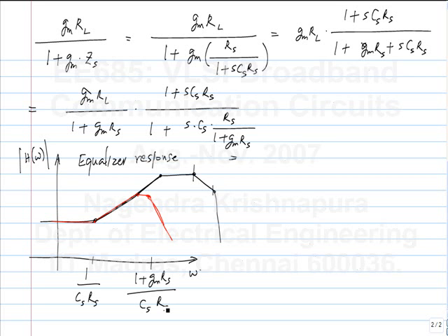Now the difference between this type of boost and what you get with a second order system is that in case of the first order with a 0, you can practically get any boost you want. That is boost here I am talking about compared to the DC value. That is what is of concern. Of course, you can't have the gain to be very small, then you will end up transmitting a very small signal. But besides that, essentially boosting high frequencies or de-emphasizing low frequencies, they are the same thing as far as the equalized response is concerned.